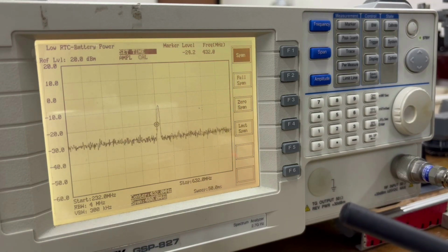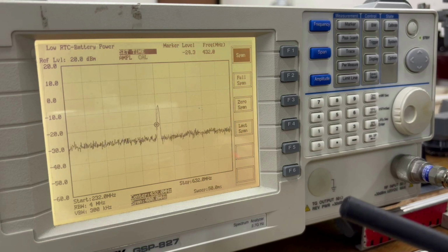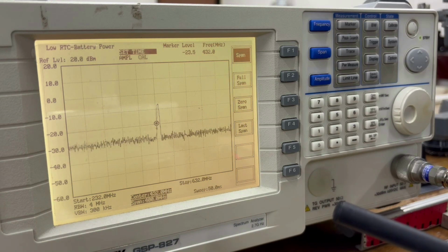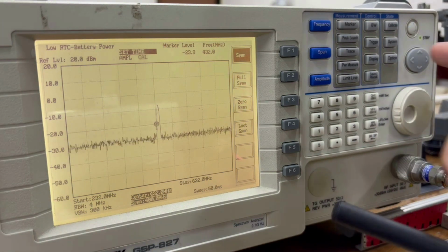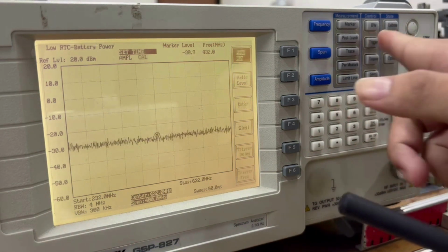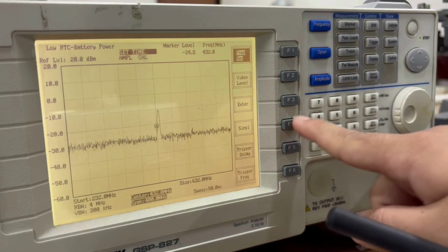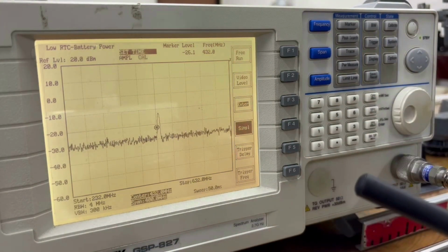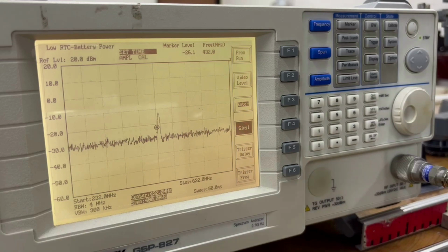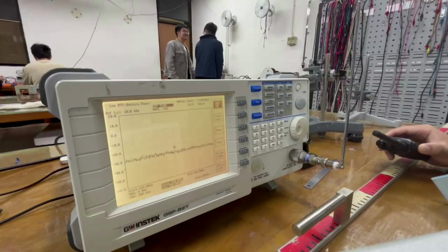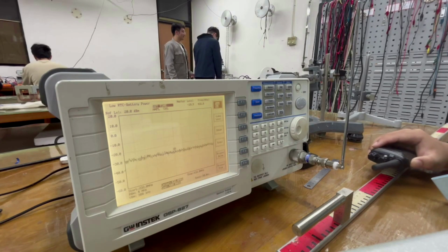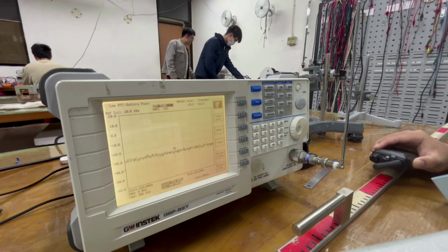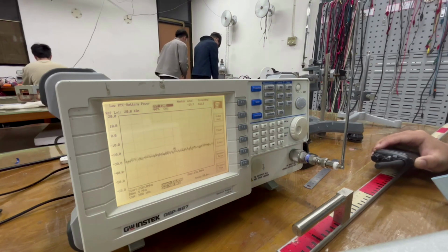So now let's see our trigger level. It gets triggered as soon as it sees the signal. If we change this to single after pressing the walkie-talkie, it will register the frequency, and the signal will be stuck onto the screen. For the second part of this experiment, we first lengthen the antenna to the most.